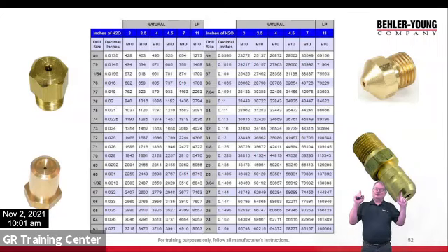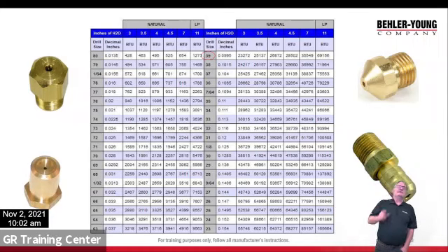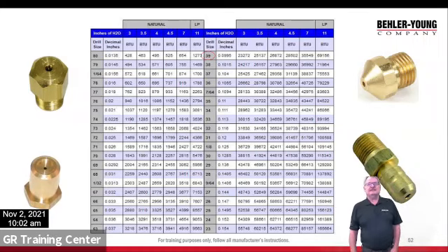The second is what is our volume. So depending on the size hole in these orifices that are feeding the burners are going to dictate the capacity of each one of those burners. So if I look up at the top here, you'll see drill size 35. So if you go down that list, most of them aren't in sizes like 3/8, 3/4, whatever. It's a number. So each one of those numbers, this is a drill size. Okay. And you can actually get a drill kit for these.